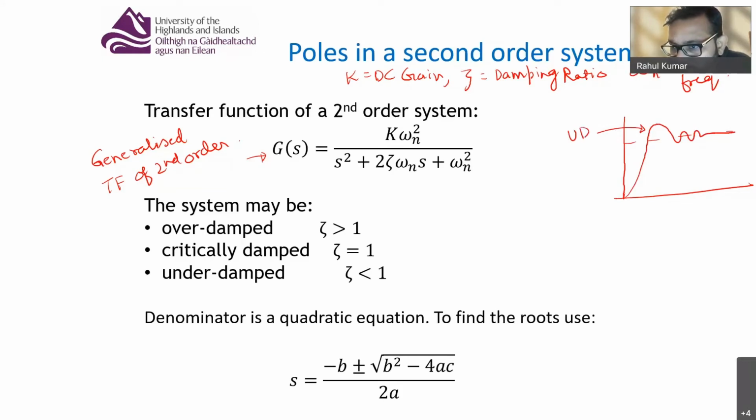Underdamped system. Then you may have an output for a critically damped condition, where the output rises very quickly, or fairly quickly. There is no overshoot, there is no acceleration, and your output gets stable around the desired value, right? Very nicely. So this is your critically damped system.